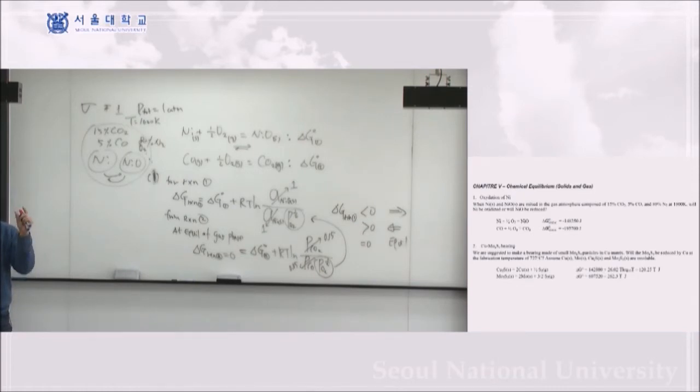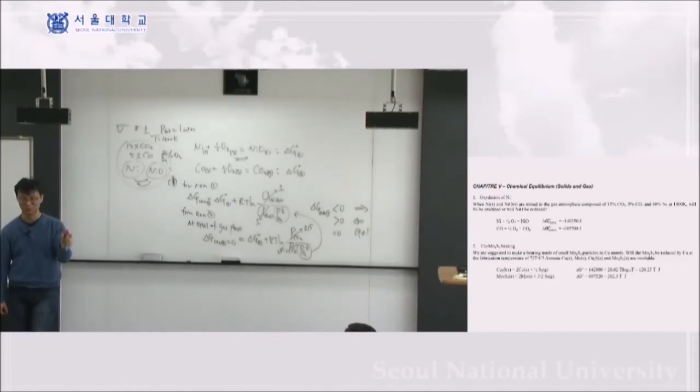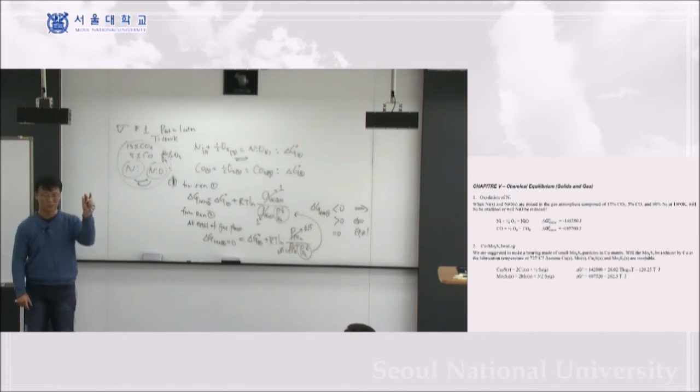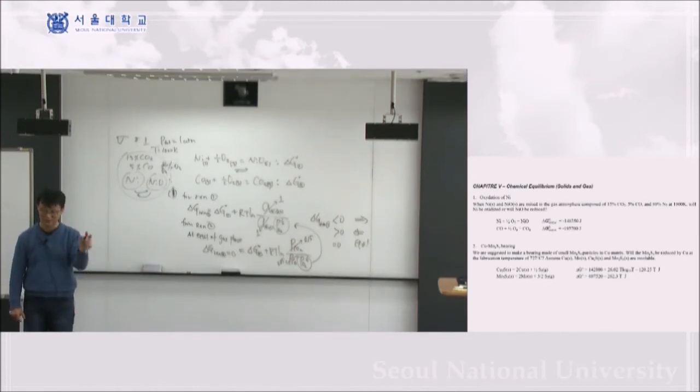Pure doesn't mean, in this case, one element with 100% purity. It's a solid phase, a pure solid phase, versus a solution phase. Theoretically, you can even say a stoichiometric solid phase is the pure solid phase, with activity equal to 1. When a certain ratio of the atomic mixture can only generate that phase, I call it a pure solid phase, or stoichiometric solid phase.